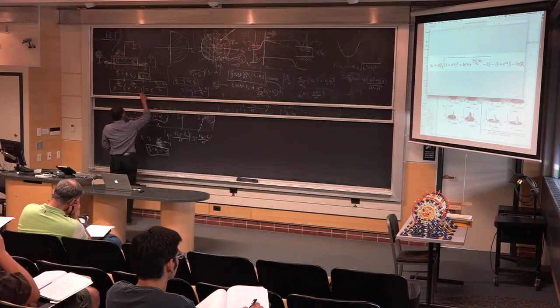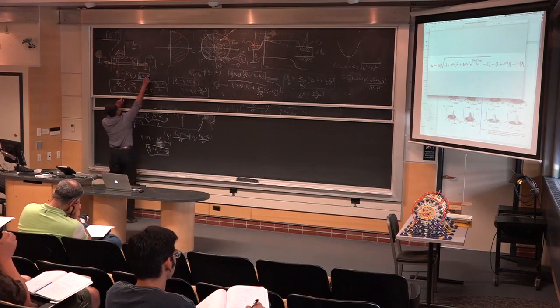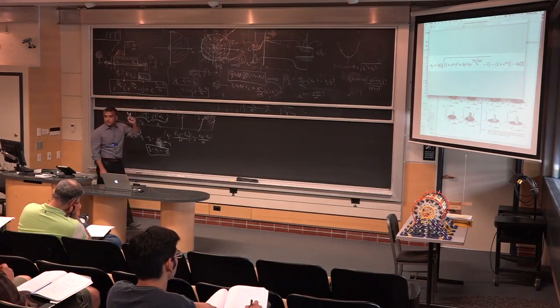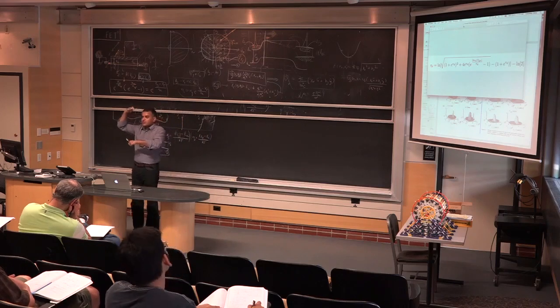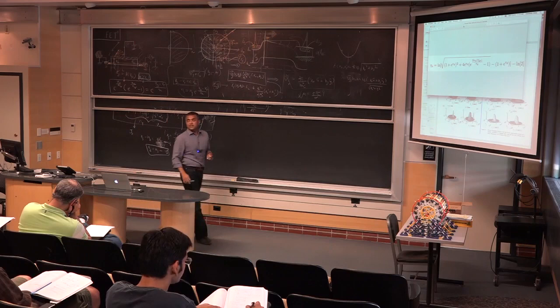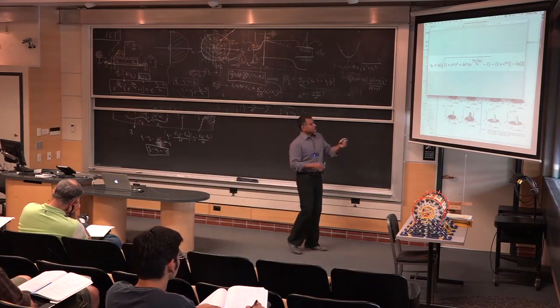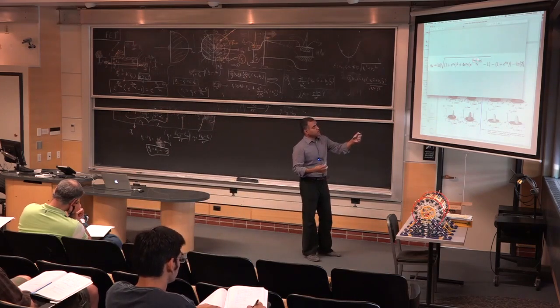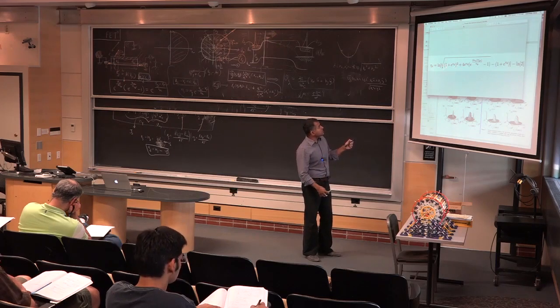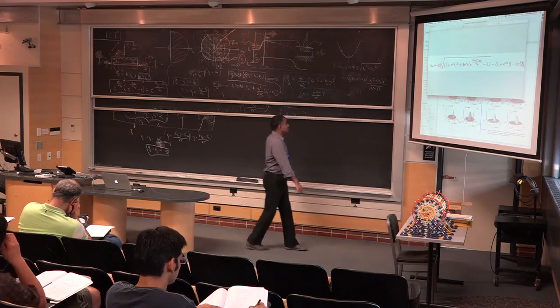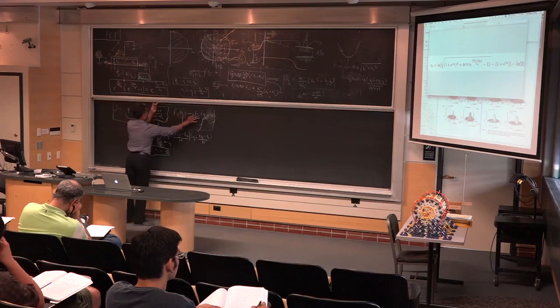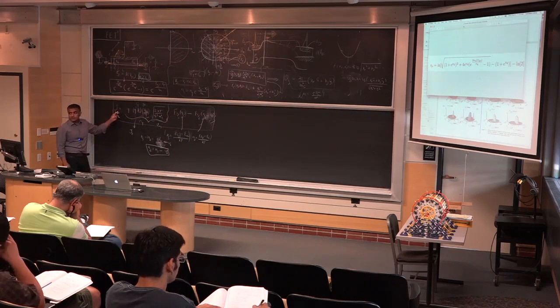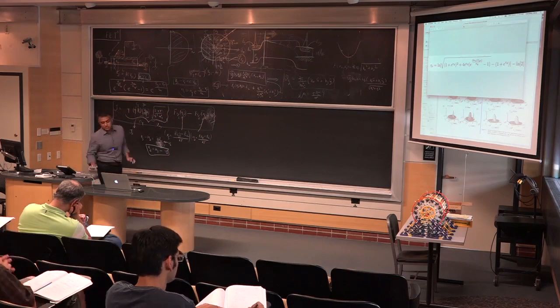solve this first, find out what is NS versus VD. First find that out. Right? And this has nothing to do with the MOSFET at all, actually. It is just a MOS capacitor, right? Metal insulator capacitor, right? Once you find that out, you have a tabulated value already for you, NS versus VG. And then you apply drain voltage, and you just evaluate this term, eta sub s. And once you know eta sub s, plug in here, got your current. Does it make sense? I mean, that's the whole story of the ballistic MOSFET.